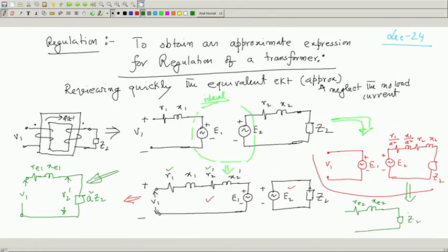But here you write E 1 by E 2 is N 1 by N 2, that is strictly. So, it is V 1 dashed. So, this is the equivalent circuit referred to load side, secondary side, and it is the equivalent circuit referred to primary side. Okay. Either of this or you can live with this, but this is somewhat complicated, complicated in the sense computationally it is difficult. You first know this is your V 2, this is whatever current it is delivering, things like that. Anyway, you know how to handle it.